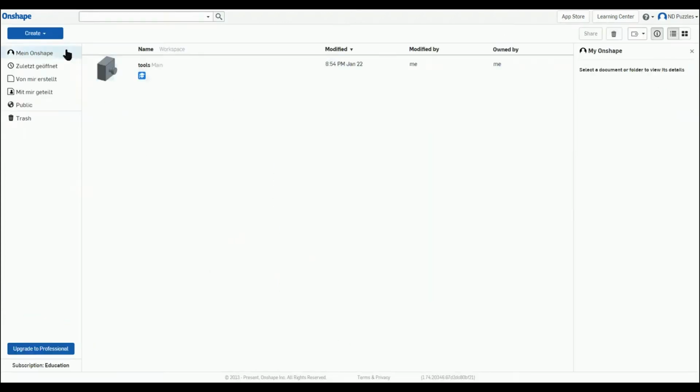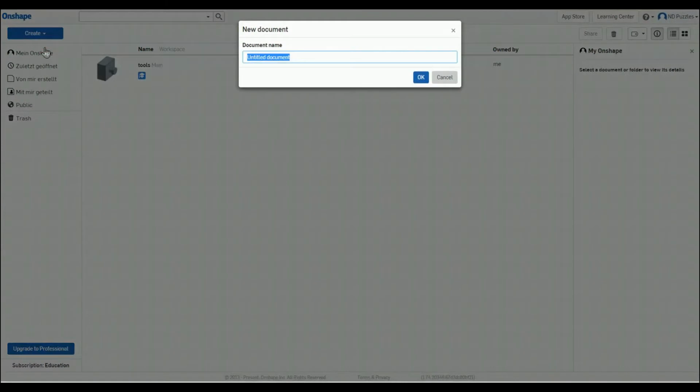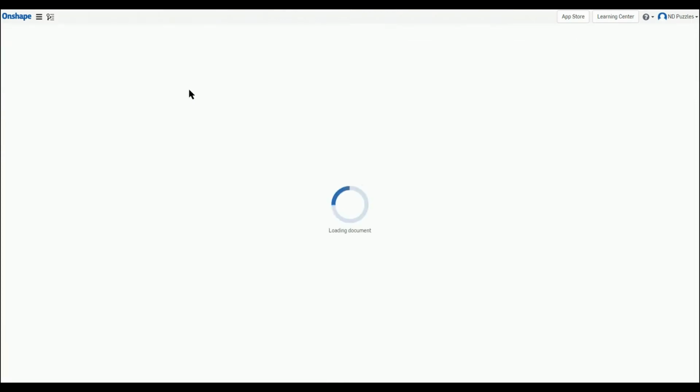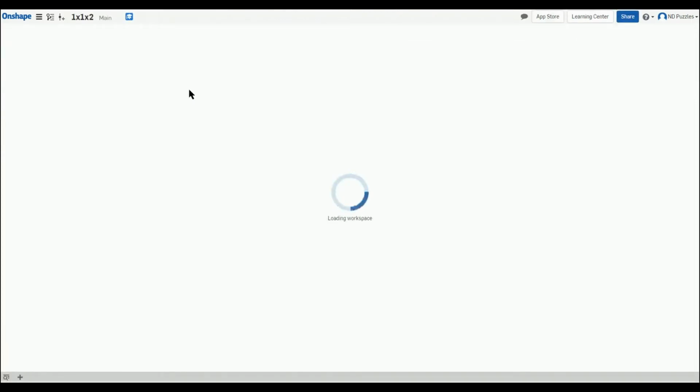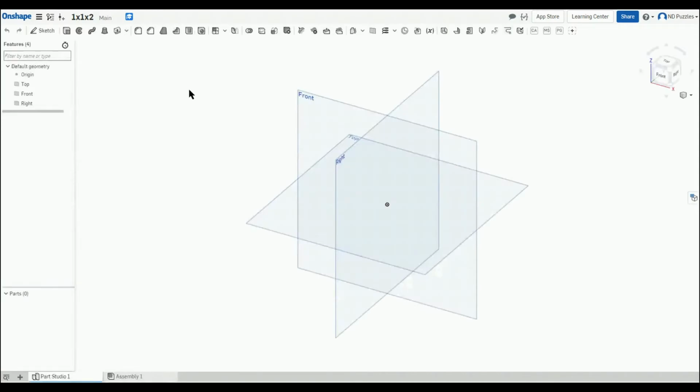That being said, we can now start to design our puzzle. First of all, open a new project in Onshape. Now you can access the three main planes: top, front and right. As a first step, we obviously need a solid to work with. To get that one, you could either extrude a sketch or just use the polyhedron generator you installed last time. Although that would be easier, I will now show you how to create a sketch, as this is a very important tool of a CAD software that you should really train yourself at.